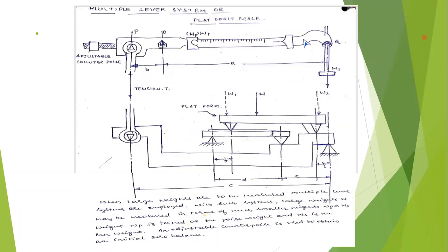See whether the beam moves up or down or is exactly at the center. By adding or removing rice, see that the beam comes to the center position. The place provided for the oscillation should come exactly to the center position. That indicates the weight of the bag, which contains 43 kgs of rice. So this is the principle of operation of the multiple lever system or platform scale.